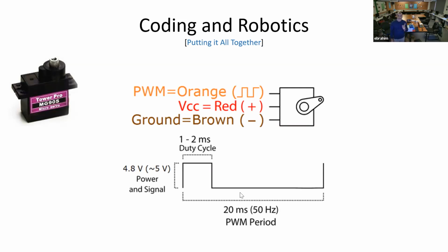The servo motor specification is telling us that every 20 milliseconds, which is the period of this, I must provide a signal with a particular pulse width. If I send a signal every 20 milliseconds, the pulse you see here must vary between 1 millisecond and 2 milliseconds.